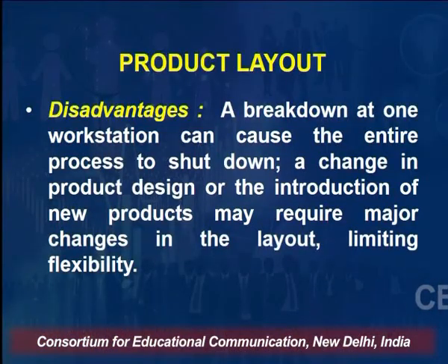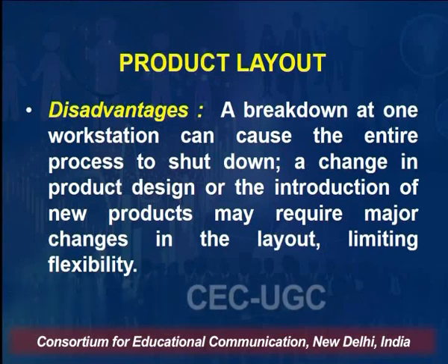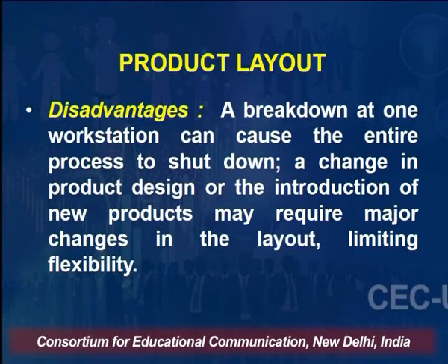Let us see the disadvantages also. Product layout: a breakdown at one workstation can cause the entire process to shut down. A change in product design or the introduction of new products may require major changes in the layout, limiting flexibility. As I was referring earlier, these product layouts are generally designed to be customized for a particular product. You cannot introduce any new product very easily. So flexibility is less over there.